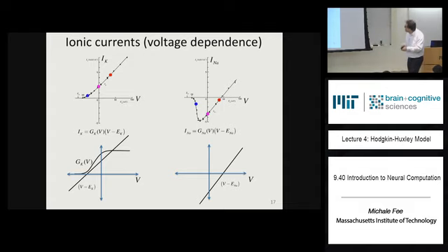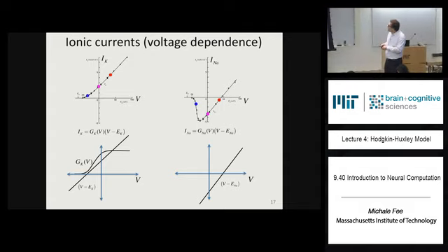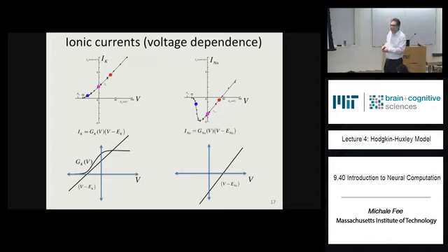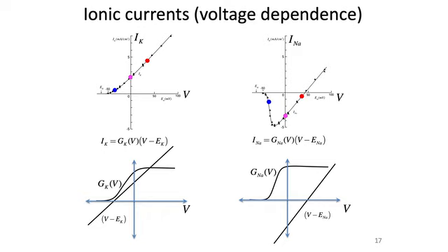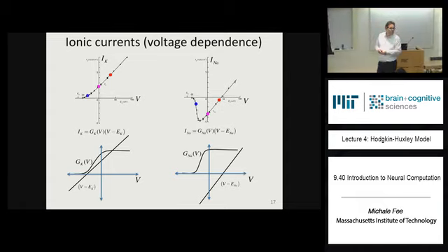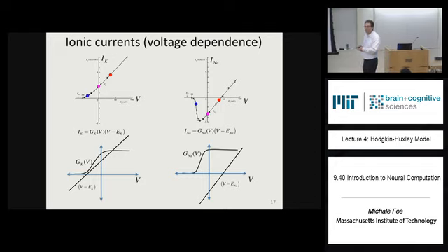Now, this is linear. This is linear. So what does the conductance look like up here? Good. This is 0, but this is big and negative. So what does the conductance look like down here? Good. Starting to look pretty familiar, right? Boom. It's exactly the same. Both of these conductances are off at negative potentials, and they turn on at positive voltages and remain constant.